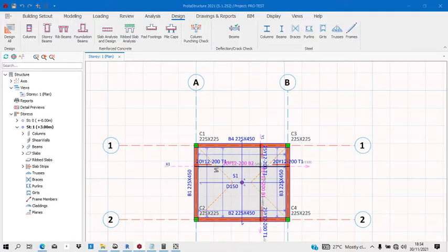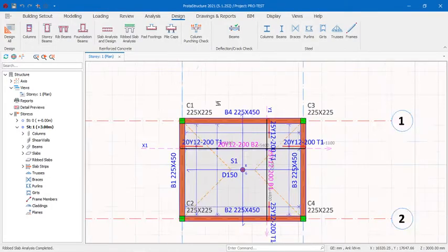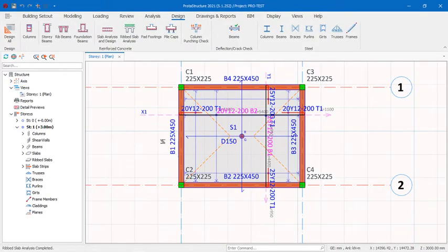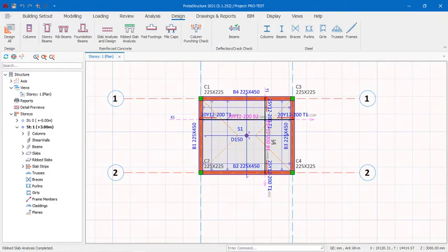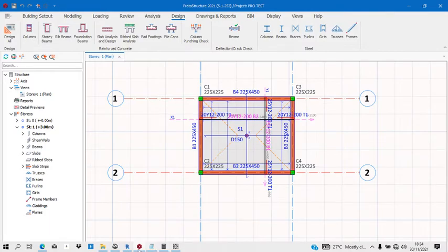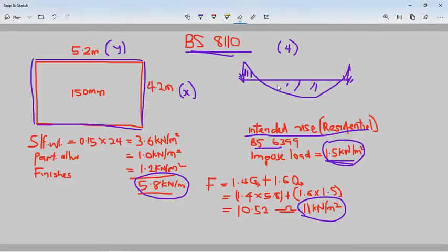I don't expect that you just jump into the software and say okay, this is the slab, we place beam, we place that, and that it will just come out fine. With what I've just showed you now, with this case and the initial simply supported case, you can see that there will be fixed end movement here, and there will be span movement here.